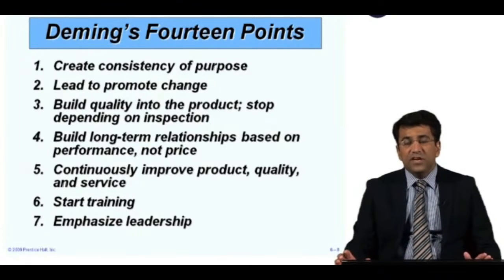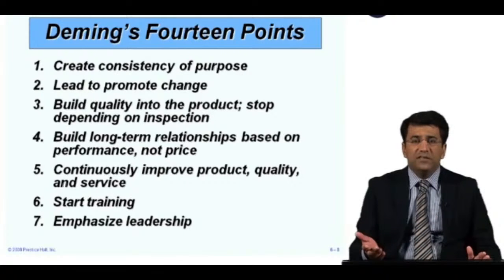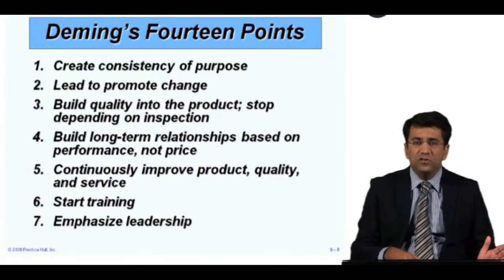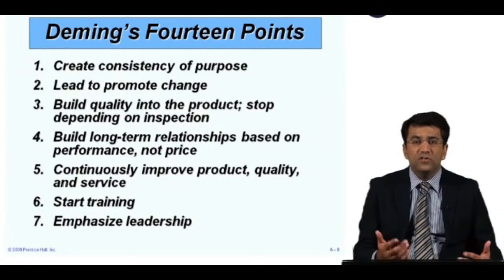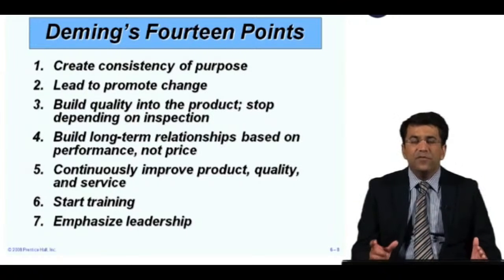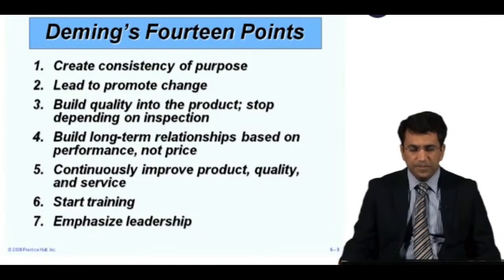So what was the traditional view about quality? We have an inspection department who usually inspect the different products and services, and finally we decide that this product is acceptable and this product is not acceptable. But now that is not the case. Now we always try to prevent defects right at the first stage in order to avoid inspection, because inspection also involves some cost, that adds to the cost of quality, which we have already discussed. So preventive management is always so important when we talk about TQM, total quality management.